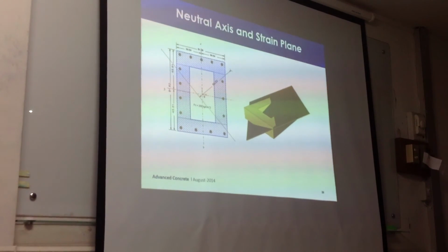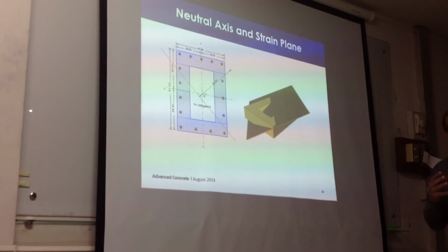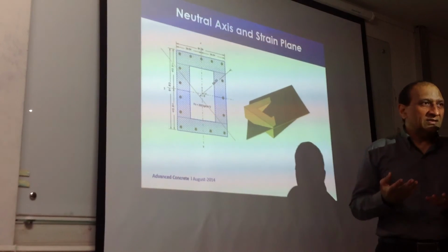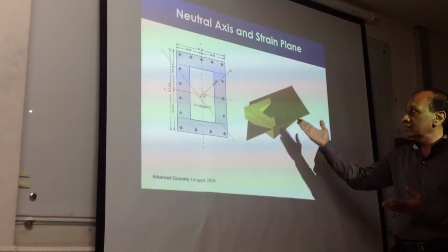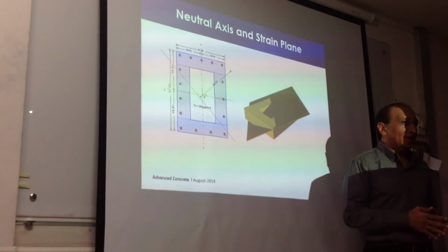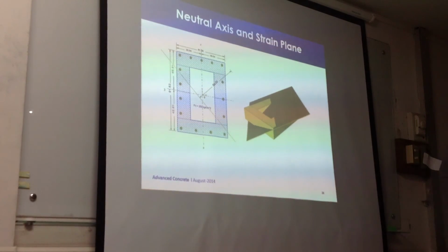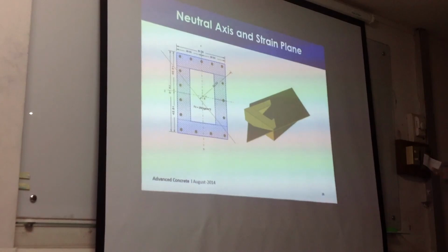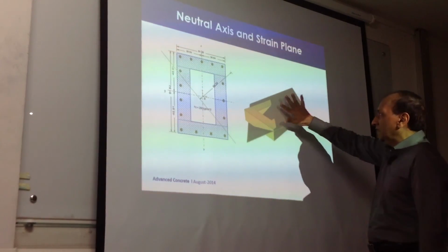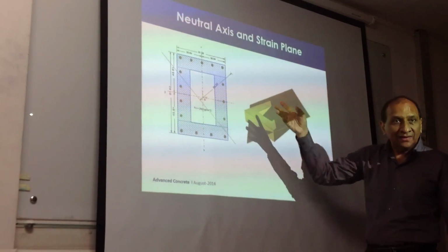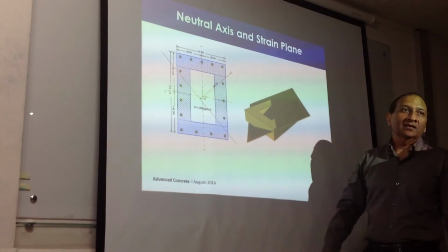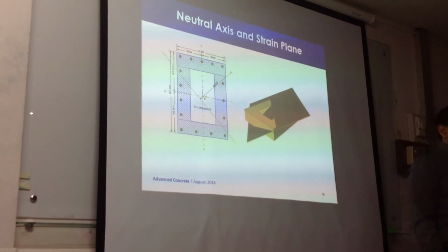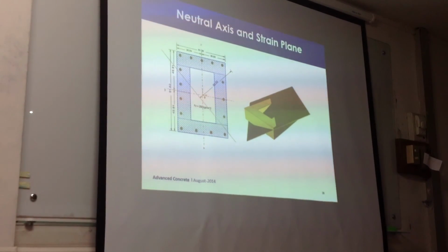So the concept of a neutral axis is a convenient one in a certain case only, when we assume the plane sections remain plane and they intersect the cross section only one time. But in reality, these deformed sections are warped and could be anything, and they may intersect the cross section more than once, like in deep beams. We will talk about that later.